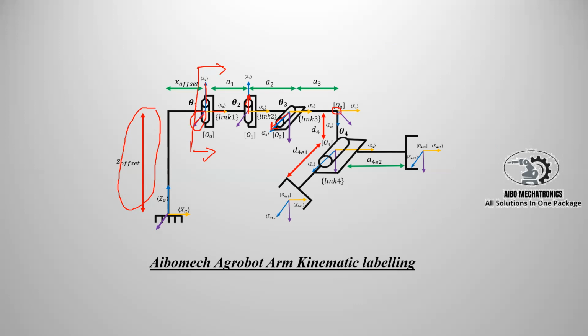I don't have any revolute joint here, but I suppose it because I carry the axis of Denavit-Hartenberg. The fourth one is also in the direction of the revolute joint. I suppose it to be like that because we have to have an arbitrary axis, so I suppose it in this direction to be simple. And the fifth one is also in here.